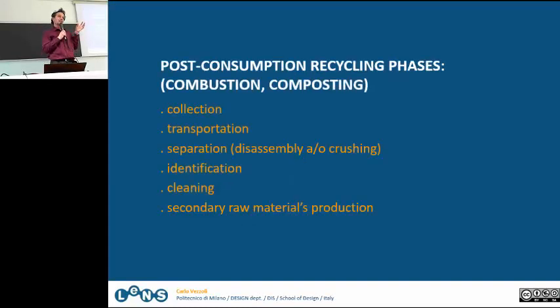And in fact, when thinking about the recycling process, it's good to understand that even this is a cycle. When designing, we have to consider that any material needs to be collected. I will put it in the bin there, and then it is transported, separated, disassembled, and then identified to know what kind of plastic this is, because one plastic is different from another. If this is a polypropylene, I cannot recycle it with a polymethyl methacrylate, because the melting temperature is different, so one will burn while the other is not yet melted, and so on. So I have to know all these kinds of things, okay?